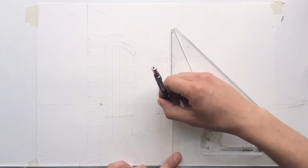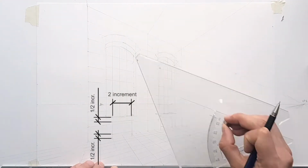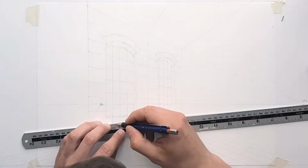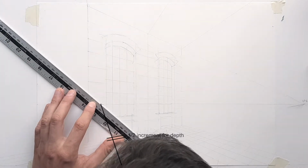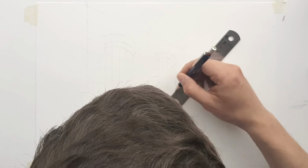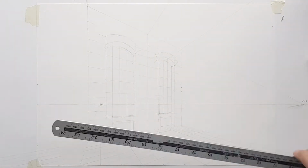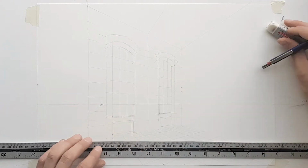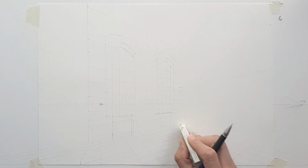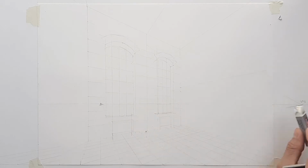For this next bit, we'll draw radiators 2 increments wide, which is a meter, and then let's shave off half an increment from the top and bottom, and also have half an increment for the depth indicated, and draw a box for the left hand side radiator. The right hand side one is going to be covered by the stairs, so there's no point drawing that. Next, we'll mark up a midpoint at the right hand side wall for the mezzanine level floor. A cross is used again to do that, and then project a line on the right hand side wall.